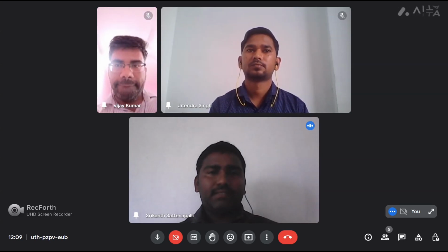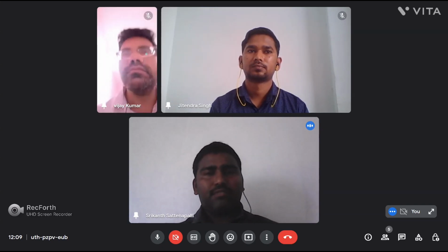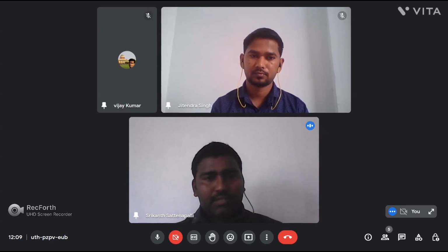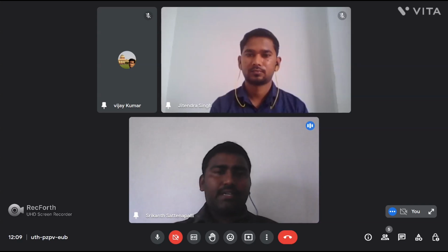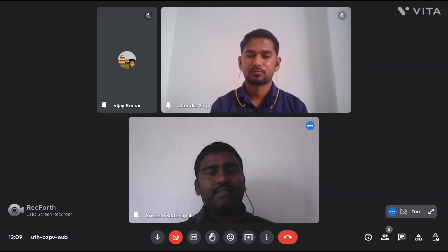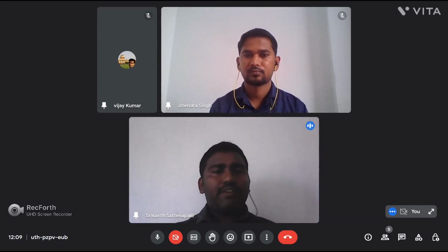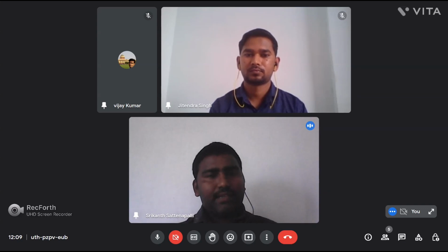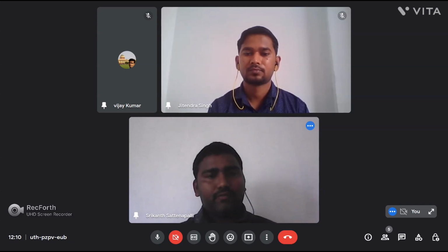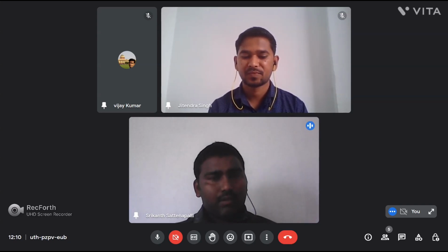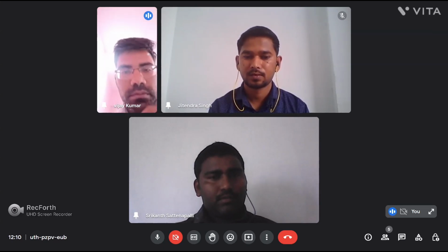If the master wants to write data to the slave, after completion of that transaction the slave gives the response in any order, which means it is not serial. That is out of order. Particularly, out of order occurs in the write response and read response. So how many channels are there in AXI? In AXI we have 5 channels: write address channel, write data channel, write response channel, read address, read data channel. 5, one is left. Okay. No problem.